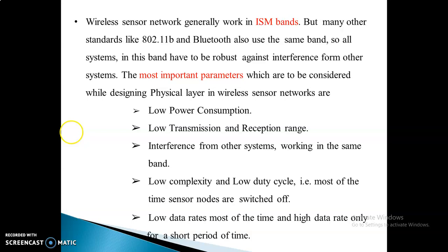For communication purposes, there is always a finite portion of the electromagnetic spectrum, which is called a frequency band. Out of this frequency band, they fix the range of usual radio frequencies. They can go for very low frequency, low frequency, medium frequency or high frequency. Low means about 100 km wavelength at 3 kHz, and extremely high means about 300 GHz with a 1 mm wavelength. So depending on the range of distance, the frequency range is fixed.